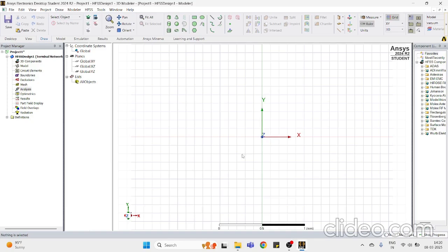And the point is, at a particular frequency, you'll be designing this microstrip line. So the parameters of the microstrip line are directly dependent on the frequency. So you're choosing mostly here 2.4 gigahertz. So for 2.4 gigahertz, there'll be very specific parameters of the microstrip line, the substrate and the ground plane. You'll be choosing them accordingly.